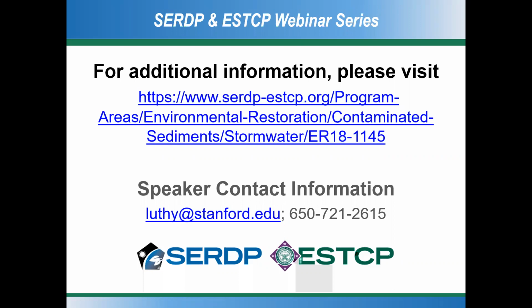Well, high flow biofiltration, that could actually work with particle removal, but biofiltration in itself probably won't work on these hydrophilic compounds. You need a sorbent material. So if you had an engineered swale or something like that, and the water's percolating through it, you could take that effluent and run it through one of these modified filters.